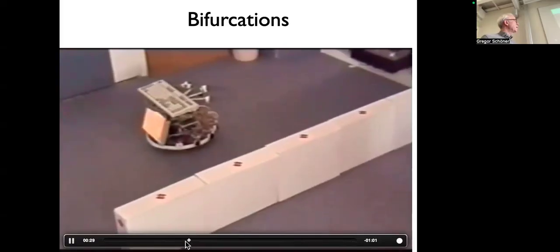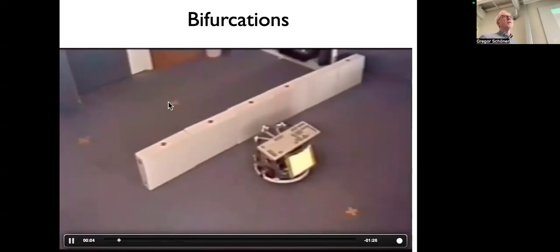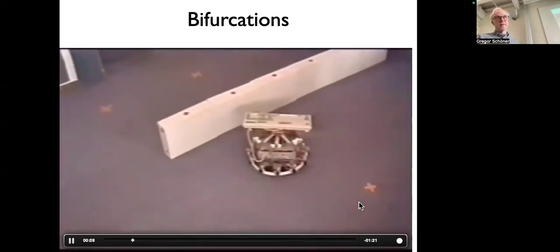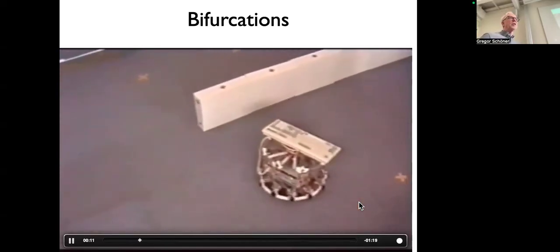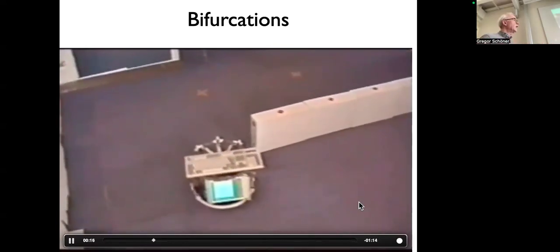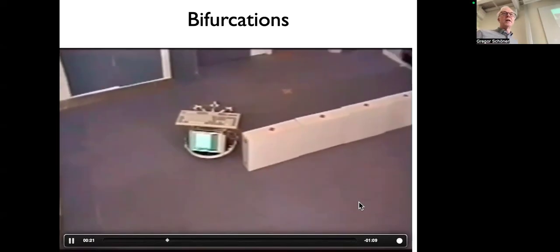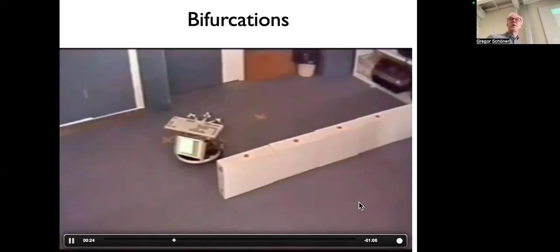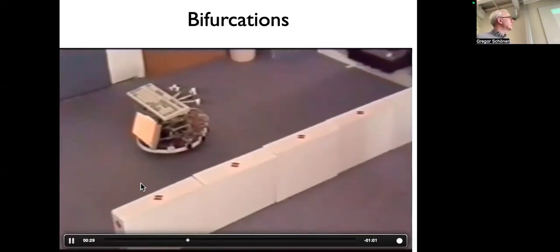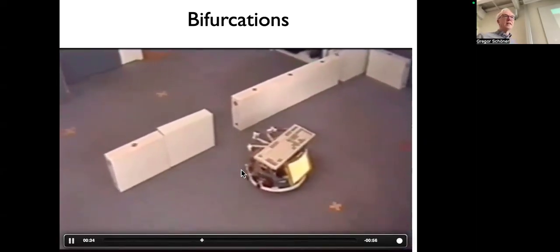For this demo, the robot actually knows where the target is. It's somewhere here. It knows it in the sense that it knows its initial position and orientation. We assumed that. Then it keeps integrating its motor commands to estimate its position, path integration, which is of course not very precise. After some time it will accumulate error, but for these short-term things it works. I'll show you later a wheelchair that we did this way, where this really works in practice. So it knows where its target is, that's why it stops there somewhere. And the only thing it does is obstacle avoidance.